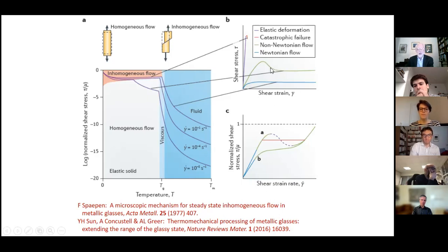So this softening introduces the possibility on a strain rate plot of having coexistent high and low strain rates at the same shear stress, which of course means you can have high shear rate in the band and negligible shear rate outside. These shear bands are certainly very interesting.